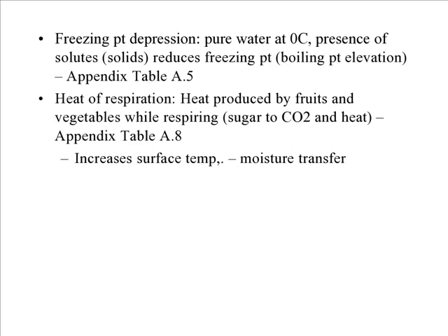Also, there's freezing point depression, where you have pure water at 0 degrees Celsius. The presence of a solute or a solid reduces the freezing point. Also, you have the heat of respiration, which is heat produced by fruits and vegetables while respiring. That is transforming sugar to carbon dioxide and heat. And that's also tabulated in the appendix. What you notice is that you have an increase in the surface temperature and moisture transfer from fruits and vegetables.